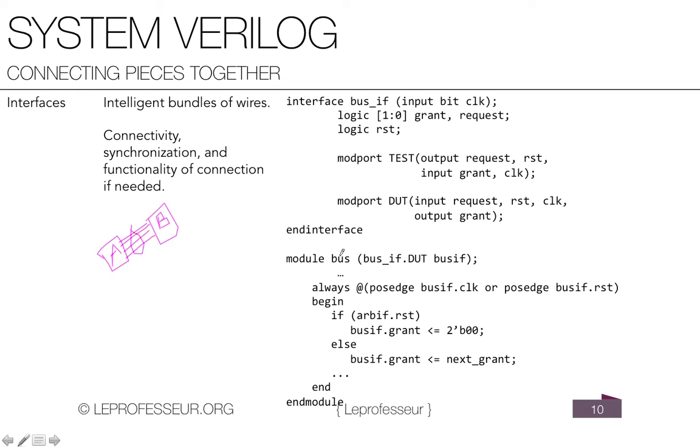And how we are using it: we have defined the bus interface and we just connected to the bus interface with the dot notation, connecting this instance of the bus interface, and that's it. So instead of writing 10 lines, we just wrote one line and got away with it, and it ensures that you don't spend your time thinking, okay, I forgot this connection, I forgot that connection. You just change it in one place.